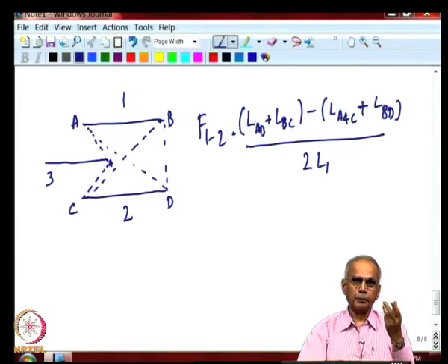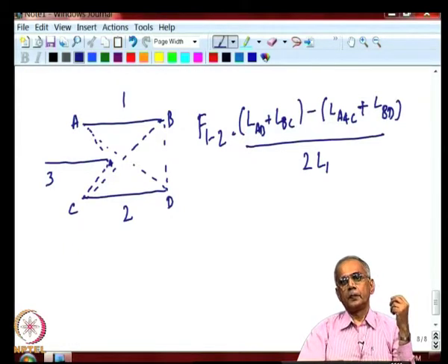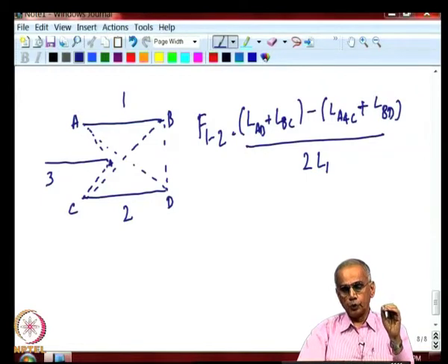As a matter of fact, there is a simple thumb rule to decide whether you have drawn the parallel strings and the cross strings correctly. If you have drawn all the strings correctly, then the parallel strings will be so drawn that any radiation leaving 1 and reaching 2 will not cross the parallel strings, and any ray which leaves 1 and arrives at 2 must cross the cross strings.